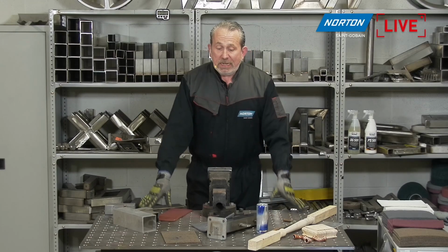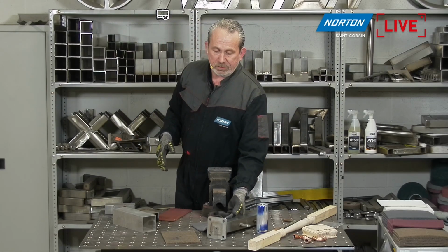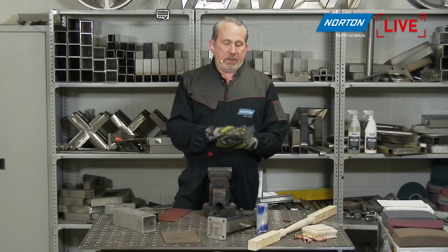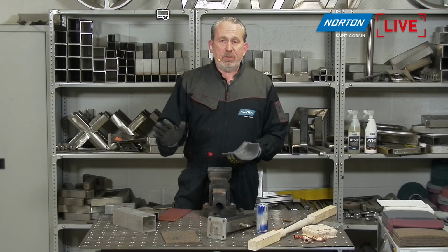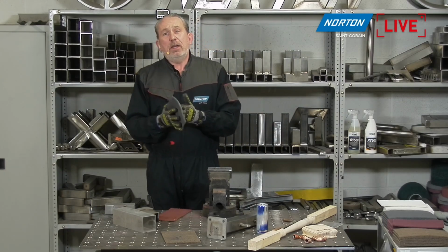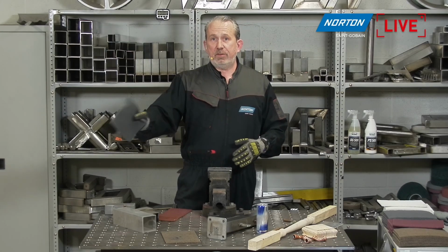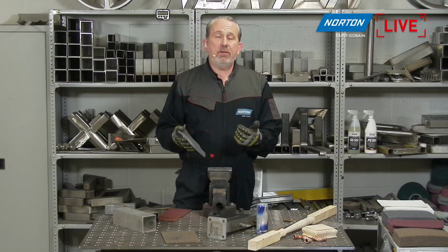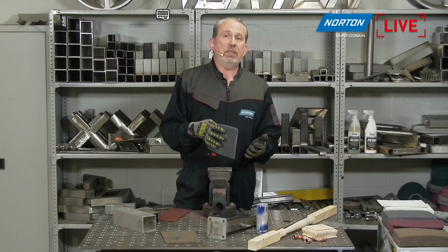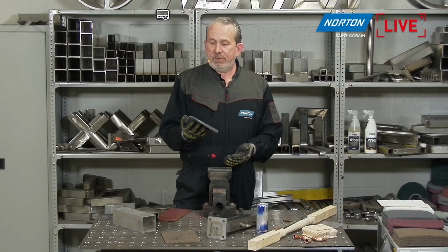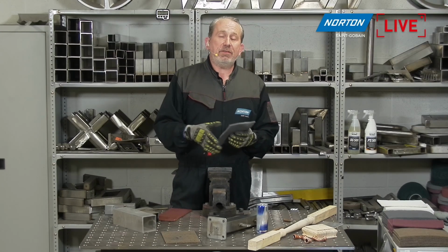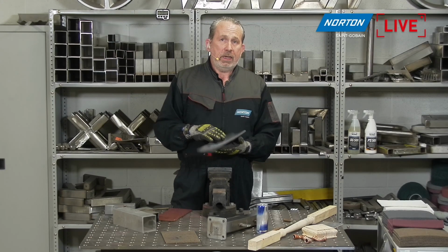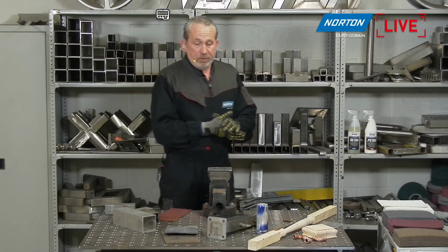Yeah, that's absolutely right. Even used a great deal in the automotive industry. This would be after you've done the filler on the body of your car after your car's been in an accident. So you've ground back down the material, you've filled it, you've sanded it down to shape, and just as a final blend over the rest of the painted surface and that filler on the body of the car, these hand pads are absolutely perfect, giving you a key for that paint to adhere onto the bodywork of your car perfectly. So if you think you can paint directly after the finish of that, that gives you an idea of the level of finish that these pads can give you. So really useful item that.